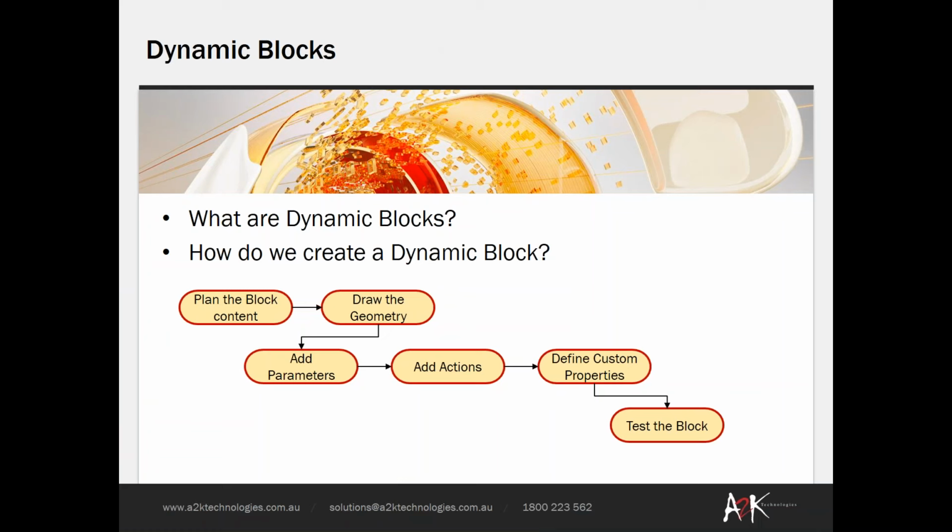What we need to do is know how the block should change or move, and then what parts will depend on the others. For example, the block will be resizable, and after it's resized, then additional geometry can display, or the block needs to flip like we saw with the door, or needs to be aligned because we've got walls that are not always on a vertical horizontal line. They may be on an angle. Next, we have to draw that particular geometry. That goes without saying.